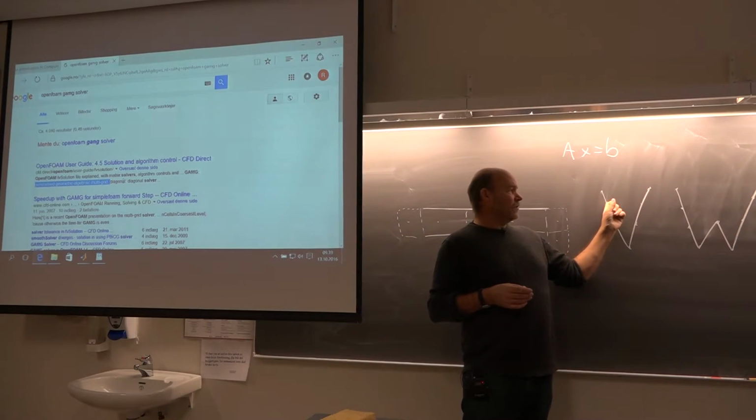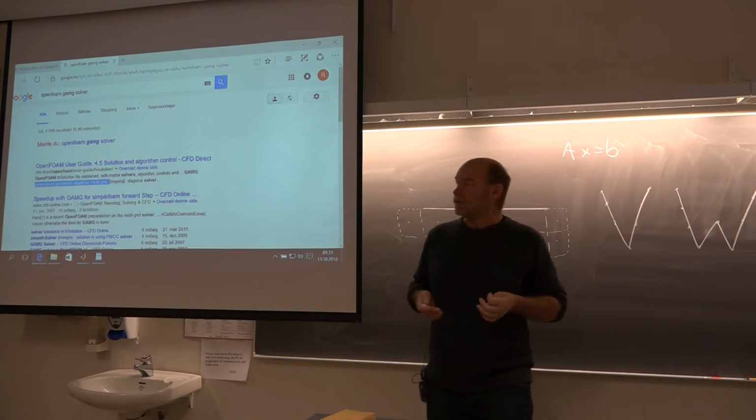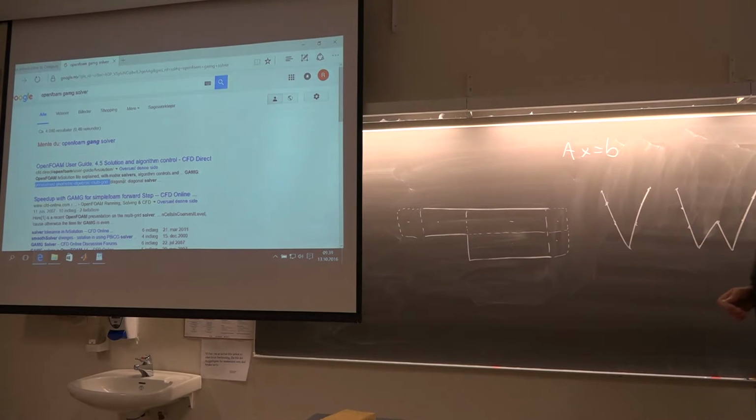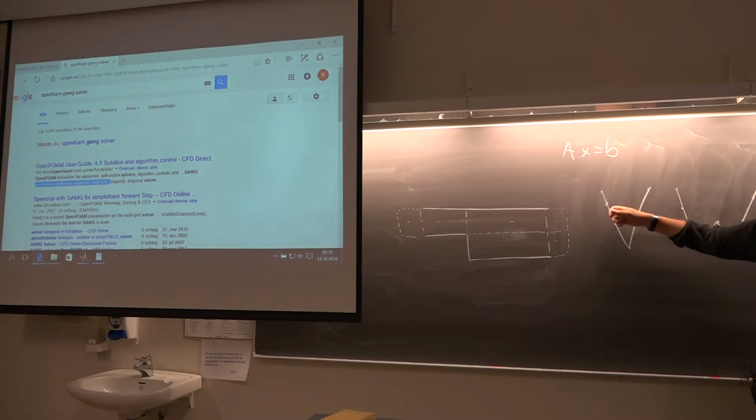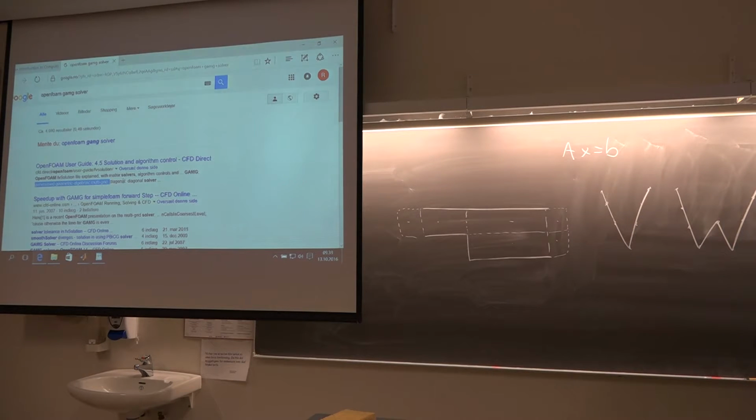Also here, it's a question of how many iterations, how many sweeps, as they call it, with Jacobi or Gauss-Seidel, you should take on the way down. For the demo example I showed you, it was 3 iterations on the way down, and then 2 on the way up again. These are numbers that will typically be input parameters into these solvers.